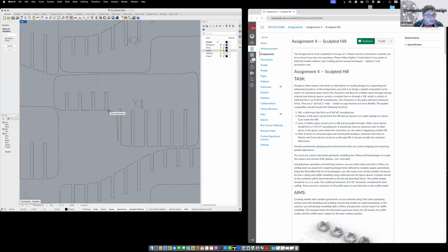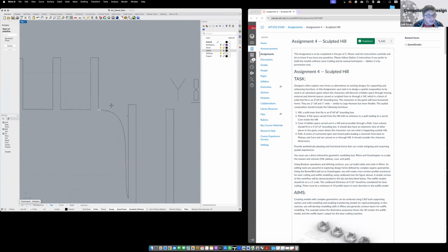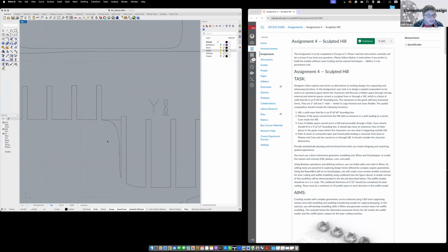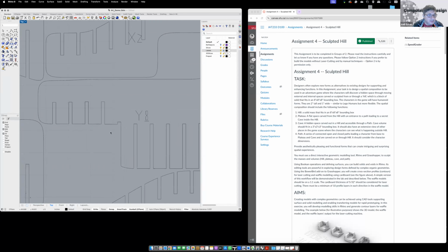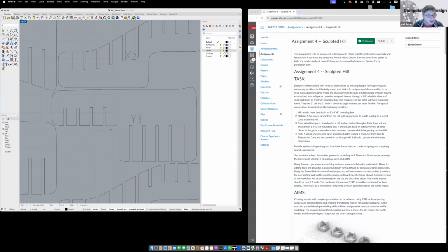So what I want to do maybe is to draw a line. Instead of this curve, I would draw a line and bring it here. Right? So this is done. Now I will select this trim. Select this as the cutting object and get rid of this. This is done. Now I will join this.